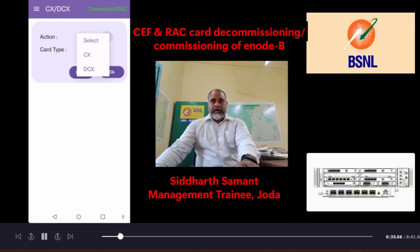Then we will reach this screen. Here in the action, first we need to select the DCX, that is for the decommissioning, and in the card type we need to select the specific card. First we are going to decommission the rack card, so I have selected the rack in the card type option, and after this we need to press OK.